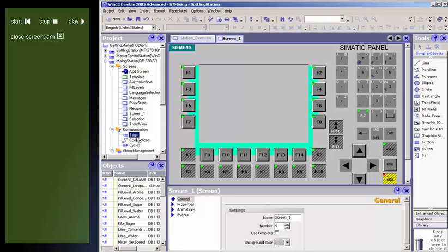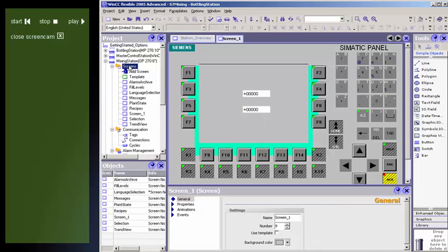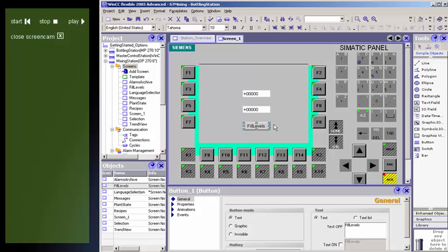The procedure is very familiar to users of MS Office. You select the line or element you want and create the new objects using drag and drop. Example: generating an I/O field automatically by dragging and dropping a variable in the display, or simply selecting a display by dragging the object into the display image.